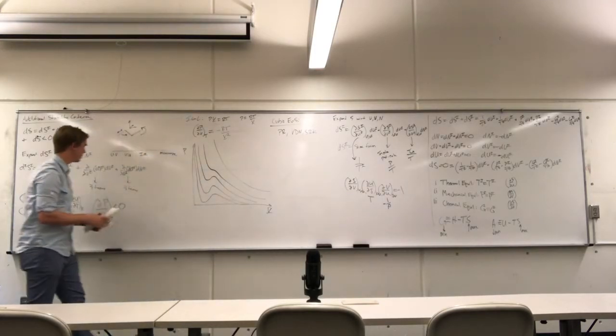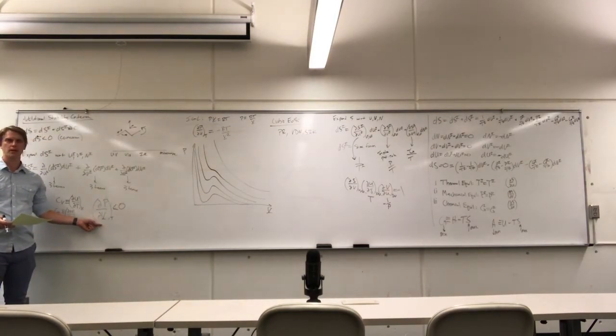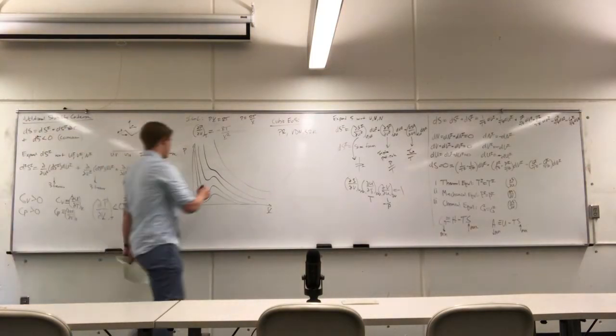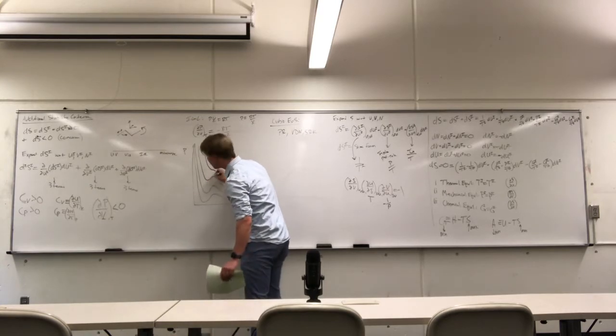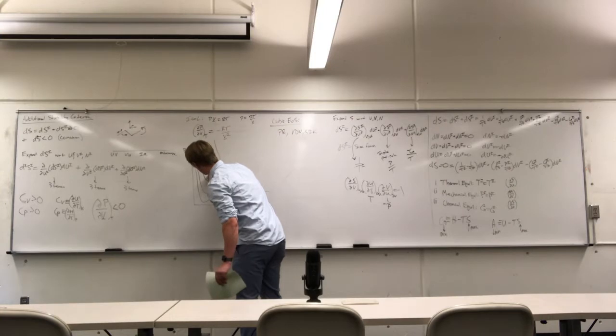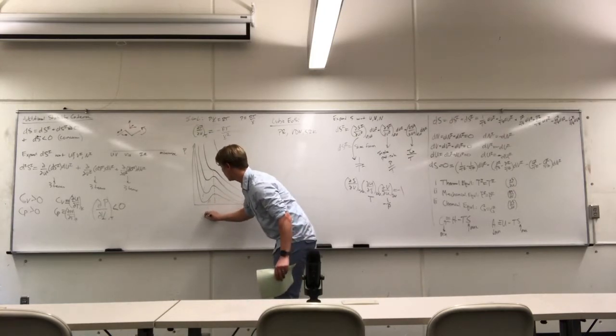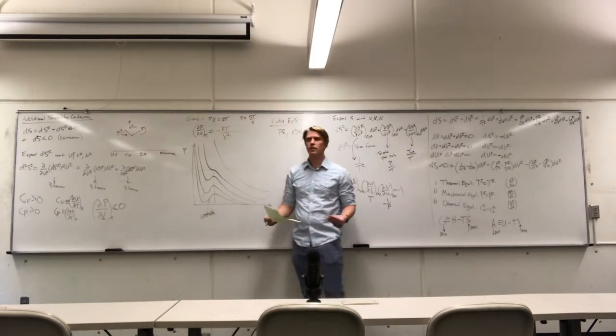Now we'll go back to our stability criteria here. There are regions in the cubic equation of state that violate the fundamental stability criteria of real fluids. That region is bound where we have a positive slope in this curve of pressure versus volume. So if I draw a dashed line here, inside of this region, this is an unstable fluid, meaning it can't exist.